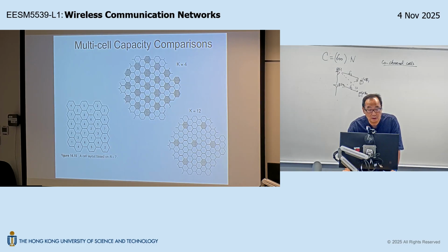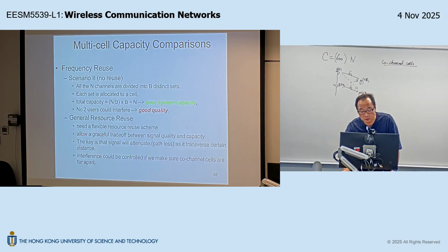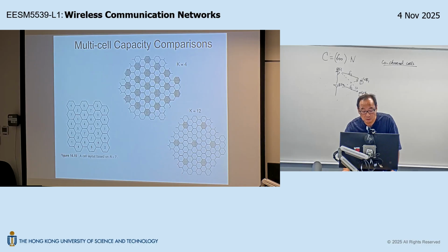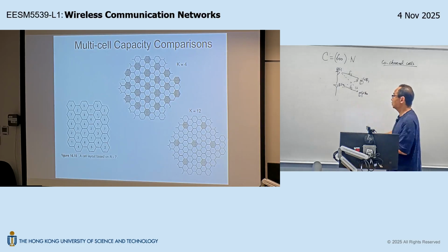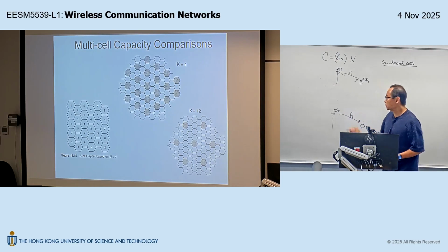Now, how would that help? Well, we mentioned that in the first extreme, if every base station uses the same channel, we have interference like this, right? So the quality of service is very poor. Now with this reuse factor of 7 example, I separate the co-channel cells by some distance. So in terms of this picture, I move the co-channel base station to here. In this case, it is using the same channel, and we still have crosstalk.